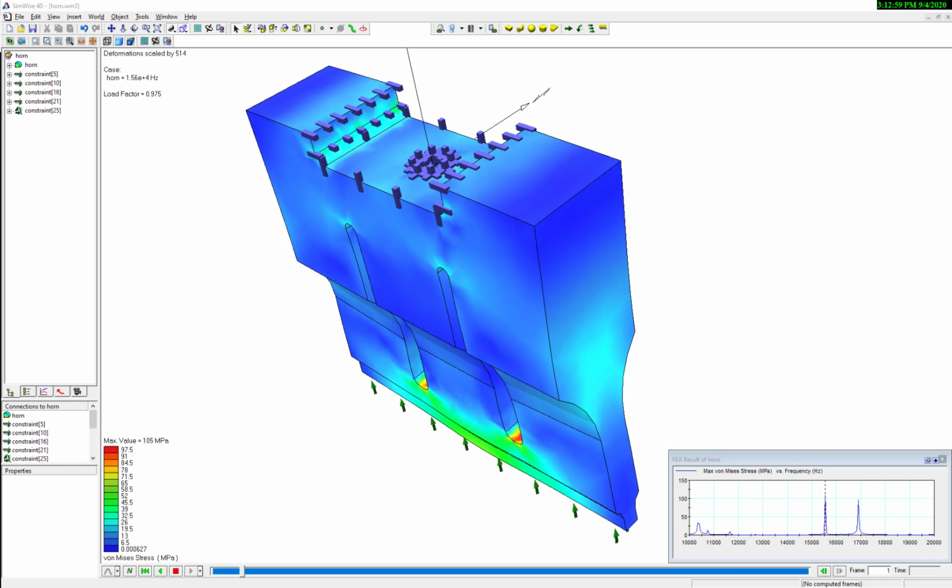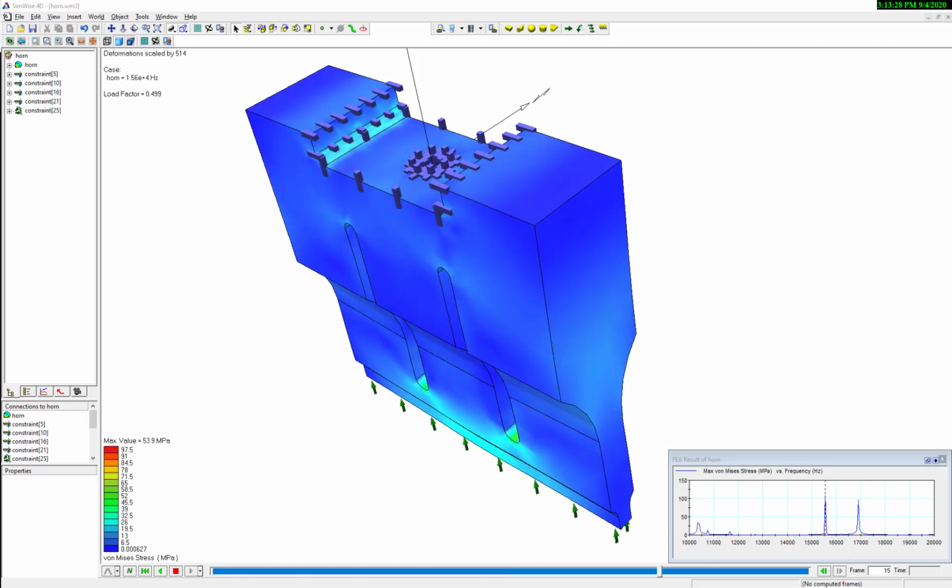Unlike modal analysis, which only calculates the natural frequencies and the corresponding mode shapes, frequency response analysis calculates the actual deformations and stresses that occur with a particular set of structural loads and restraints. It does this by varying the loads in a sinusoidal manner and calculating the resulting response at each frequency of interest. It allows the frequency ranges that could cause problems with the part to be identified.